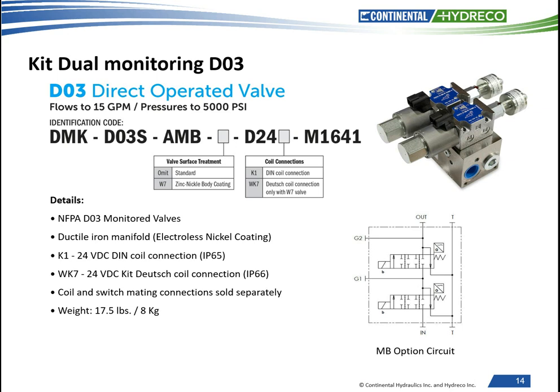Because of the Bernoulli flow forces, the difference between a 3-way and a 4-way is you do have the unbalanced flow condition, which means the flow forces will and can act on the spool, holding it in a shifted position or shifting it back when not desired.